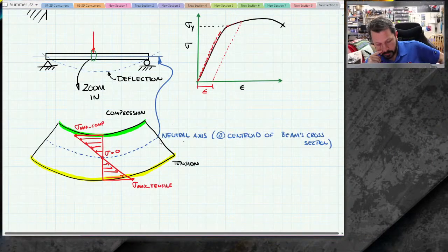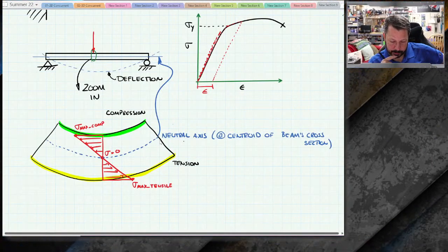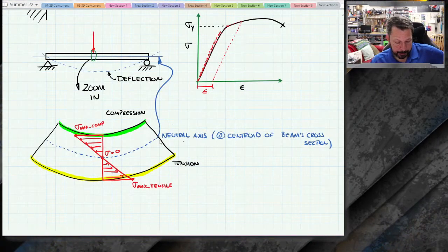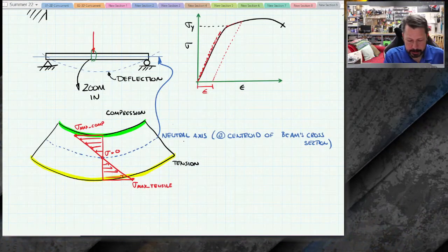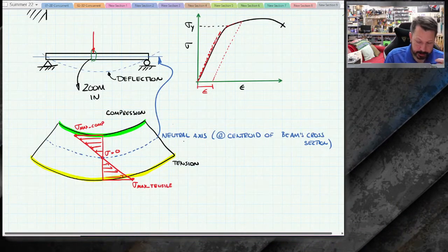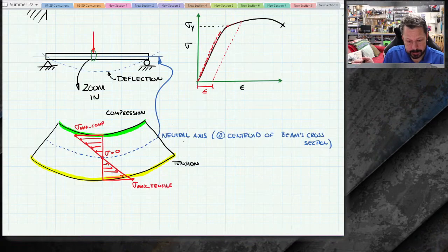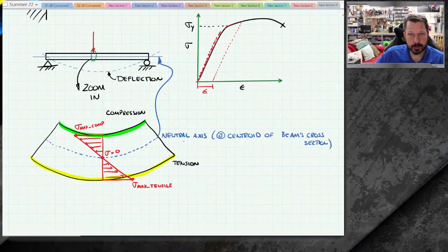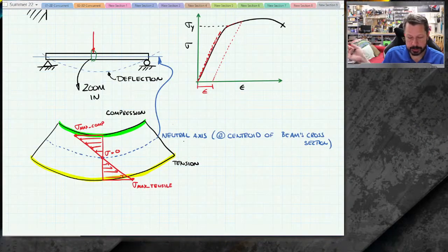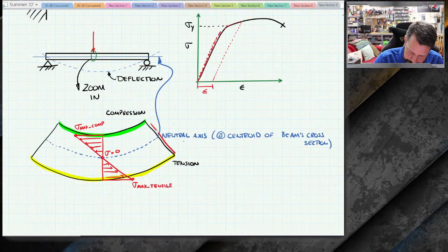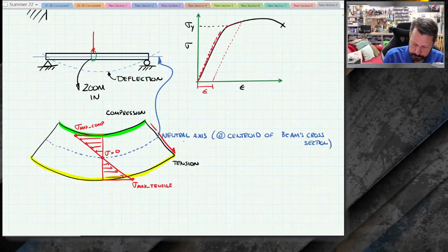Okay. Let's see, what else do we want to talk about with this right now? Oh, these internal forces. So I cut this little bitty tiny piece out of the beam, and now that I can see what's going on on the ends of what I drew here, there must be some kind of forces there because I cut it away from the rest of the beam. So on this surface, this is a shear force.